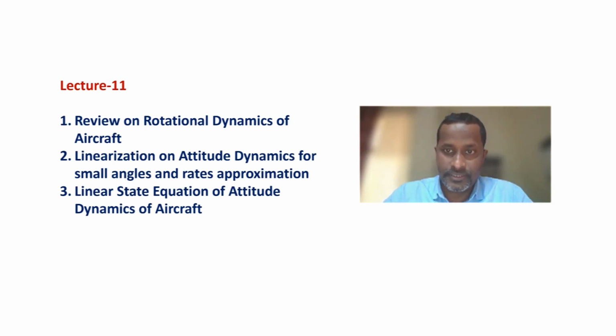After applying this assumption, we can come up with the linear form which relates the angular displacement and the applied torque and moments or disturbance acting on the system. This equation will help us to find the transfer function of the attitude dynamics of the aircraft.